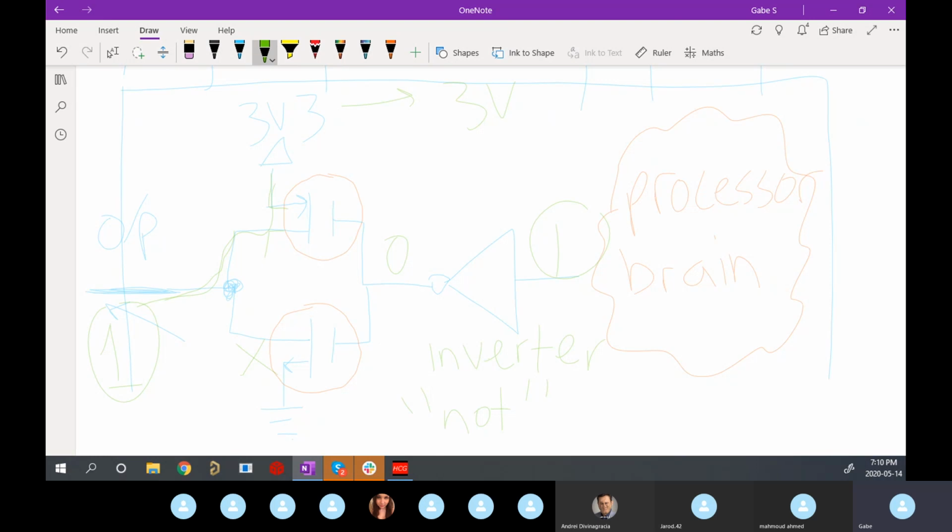The reason they do this, if you look now, your pin is connected to 3.3 volts with its own little power supply, right? If I had just connected my processor straight to the output pin, I would be drawing all the current for that pin from my processor brain, right? And this guy doesn't have a lot of current to give out. And so what we're doing here is we're creating a little buffer system where we can send the signal we want and get that on the output pin, but use it with its own little independent power source, right? Or power sink. And so this is the internals of a GPIO output.